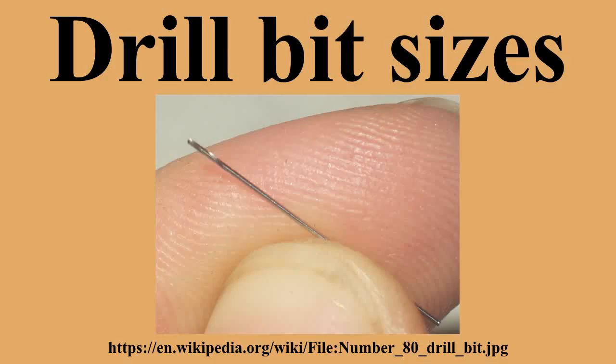Bits at size increments of 1 mm are most commonly available, and lowest price. Sets of bits in 1 mm increments might be found on a market stall. In 0.5 mm increments, any hardware store. In 0.1 mm increments, any engineer's store. Sets are not commonly available in smaller size increments, except for drill bits below 1 mm diameter.